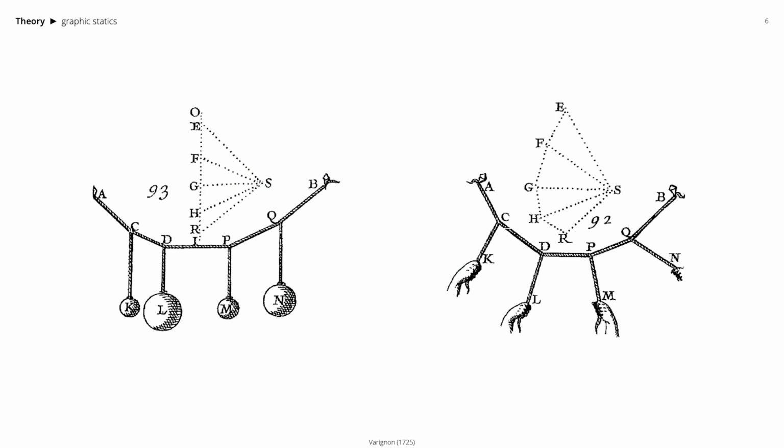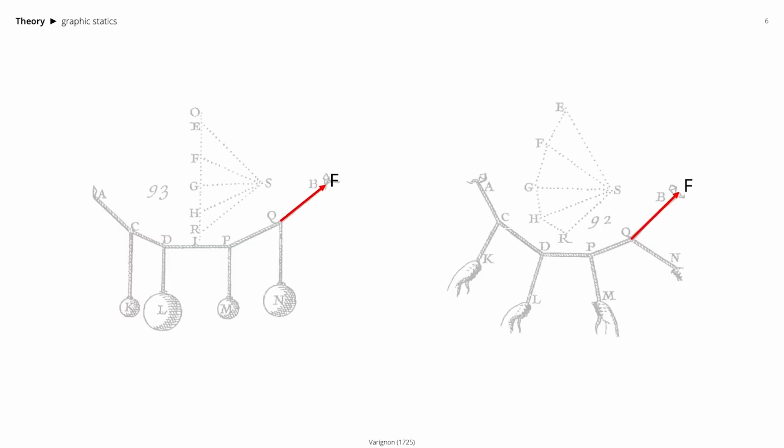Graphical representation of equilibrium using reciprocal form and force diagrams provides invaluable insight for designers and improves intuitive understanding of a structure's behavior through a visual medium that is easier to digest and more transparent than conventional arithmetic or numerical methods. The magnitude of the internal force in a member of a structure in static equilibrium is the length of the corresponding edge in the force diagram, which are parallel to one another.